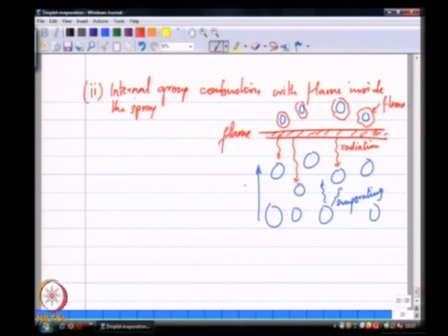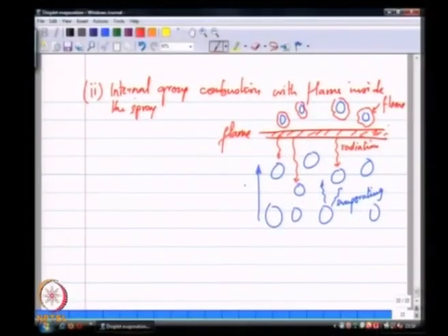So, this is a case where we have gone from a pure dilute regime. As we make our way towards the nozzle, you may have a visible flame, but some droplets are incompletely evaporated and escape the flame boundary, causing individual sparks, which are burning droplets essentially, but the bulk of the vapor release is happening inside the flame zone. The third is similar to this.